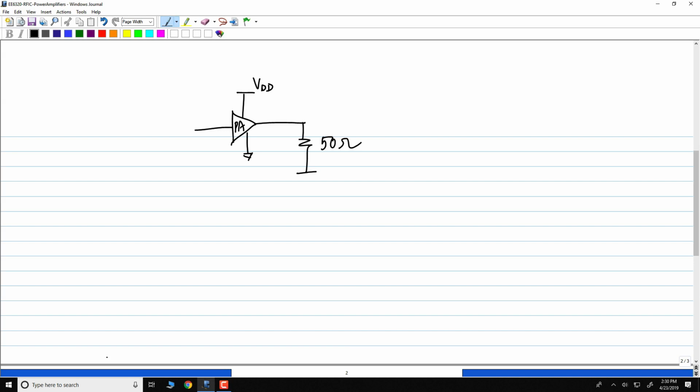What is that limited by? I want to keep increasing this power. What is the limitation? Why is the swing limited? Because swing can make the transistor settle to non-linear. What is this nonlinear region that you speak of? Like when we do the small signal analysis.